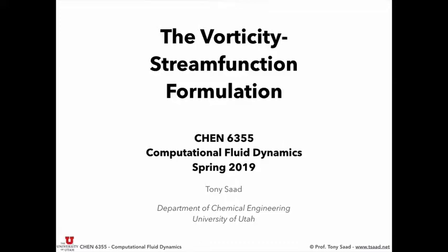We need to get our hands dirty now with doing some fluid simulations, because CFD is not only about numerical methods. It is a lot about numerical methods, but it's also about algorithms and formulating a set of equations to solve, okay? And algorithms and problem formulation go hand in hand, because the algorithm is essentially a recipe to implement your equations, okay? Today we're going to talk about the first and one of the oldest approaches to solve the Navier-Stokes equations, and that's called the Vorticity Streamfunction Formulation.